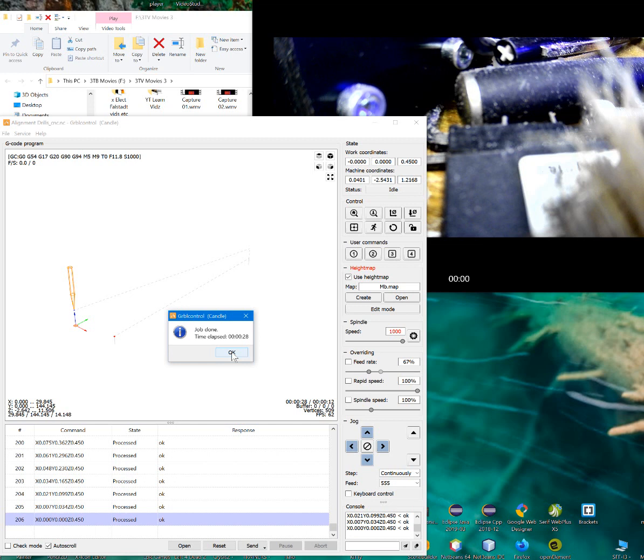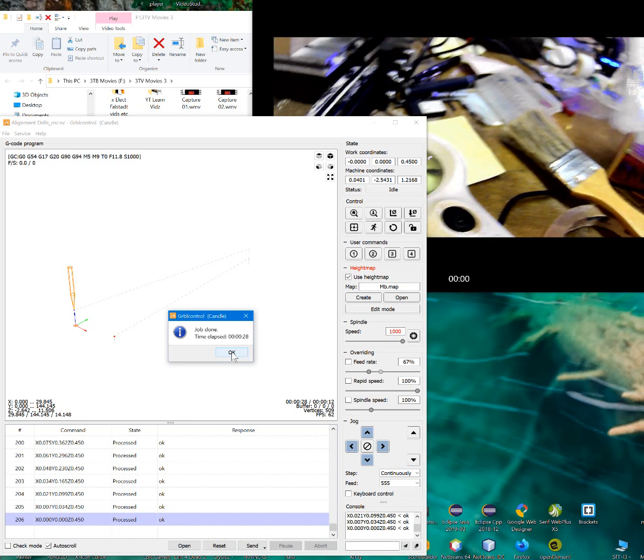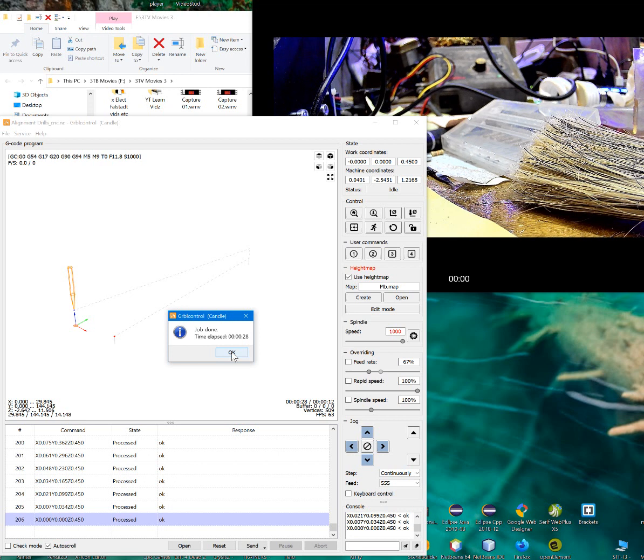What I'm going to do now is change out the tool to our router bit. Like I said, I'm going to use that V-score router because of the fine traces we're using. I haven't used one of these steeper bits with this yet. So, that's not the right one. I'm going to go for a 30 mil bit instead of the one I normally use. Shit. That's not it.